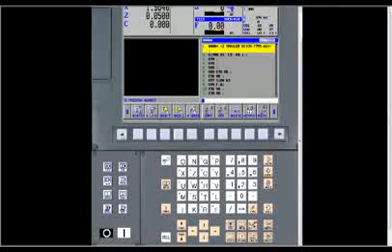And then there's the middle version, just NC Guide, and with it, you have the full capability of doing just like you did before, but you can take the programs from it and put them into a machine and actually run them. You can make a G-code program. You can import G-code programs from a CAM system into it, simulate those.